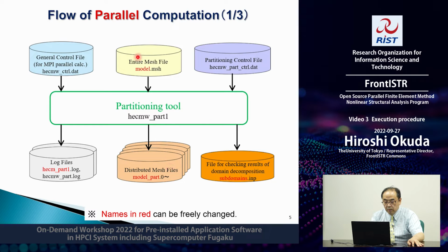The input files for the partitioning tool, which is an independent utility, are the general control file, the same as before, and the finite element mesh file, whose extension is .msh.